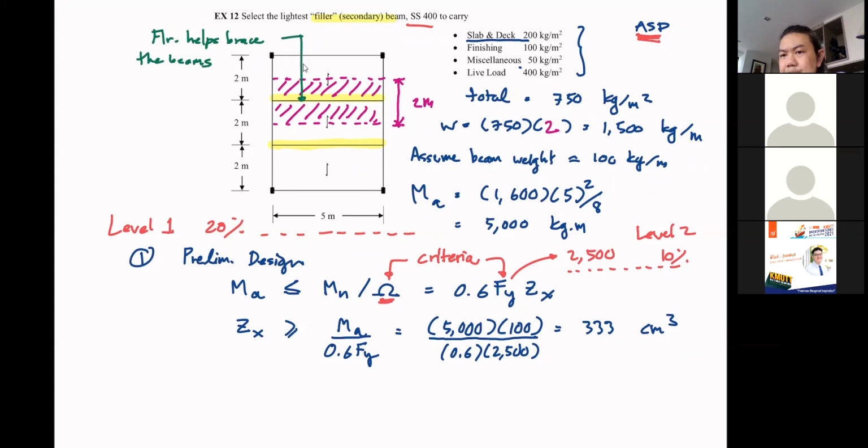Okay, but say I don't bother about the purlins and the truss because if you just look at some sections, you know that it's like 10 kilogram per meter. One meter long, it weighs only 10 kilogram. You can just put it on your shoulder and go back home with it, right? But now this is a steel section, and you carry the floor. The weight is much more significant. So you may want to include that.